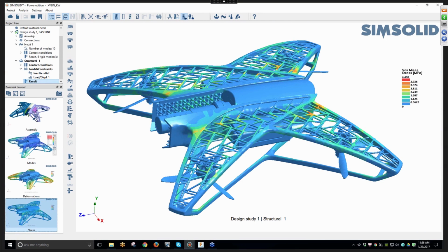If it was a combination of mesh bodies and bodies, we can solve that as well. So in Fusion, you can have these mesh bodies, which I think is kind of cool. At the same time, you can have it in an assembly with a body. We can handle both of those, and we can do the assembly between the mesh body and the body and analyze it directly. Yeah, it's pretty incredible. I mean, I don't know of any tools that will actually solve for an STL mesh. So that opens up some new opportunities for some models that I have.